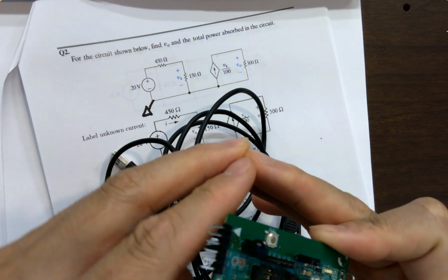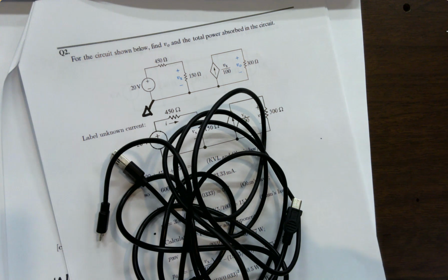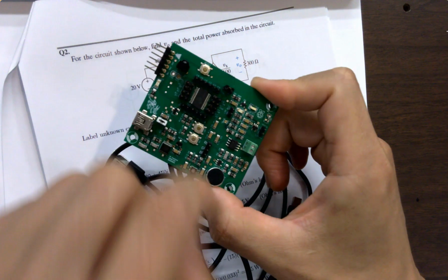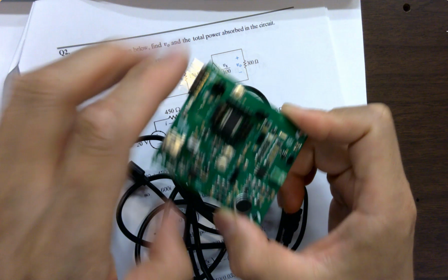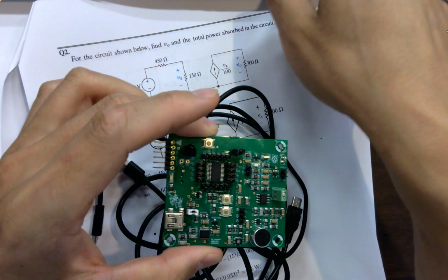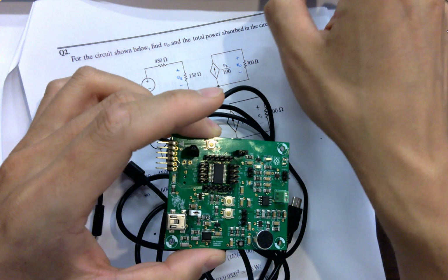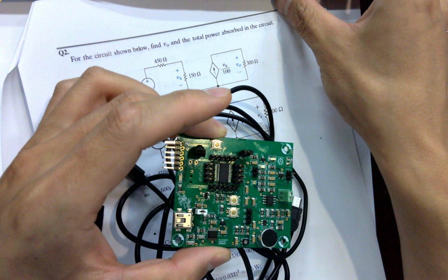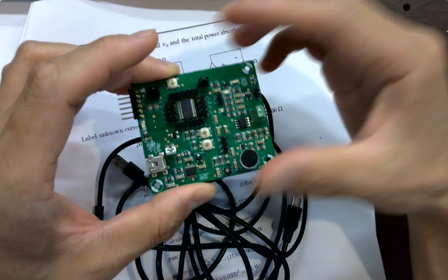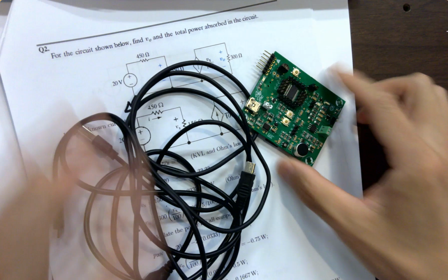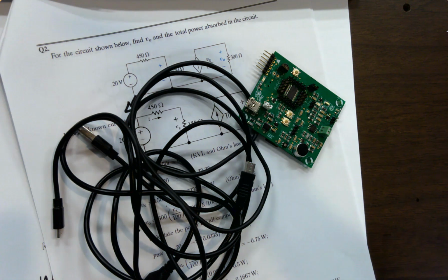Okay. Something you have to know: the ground, or the 0 volts reference, on this board has to be shared with the common ground of the laptop's motherboard. Even though you can't see it, in your mind you have to imagine there's a wire, 0 volts, shared by this and my laptop.